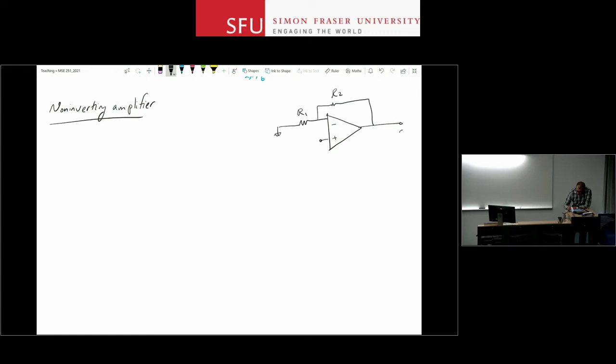But because of the limited gain, I have some limitation. I know the input-output relationship for this circuit. If the gain was constant, we did the calculation for the inverting situation, it's going to be the same for the non-inverting amplifier. So if it was ideal, it would be this. If I had infinite gain, I would have that expression. For an op-amp that has a finite gain, I will have this expression.